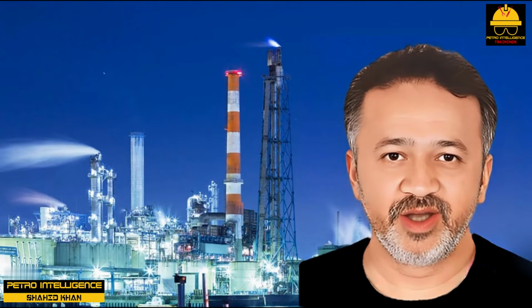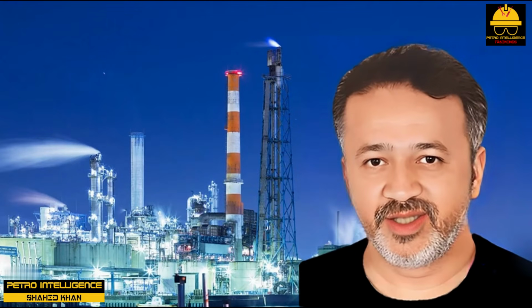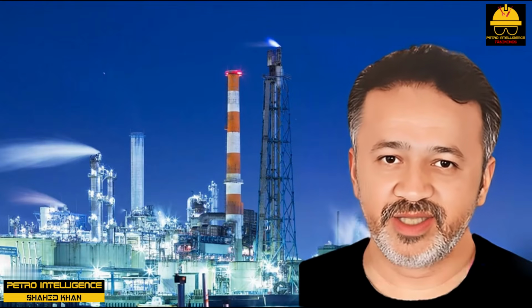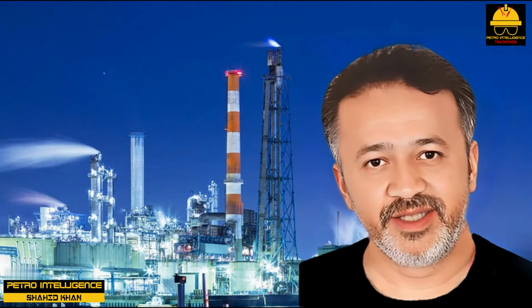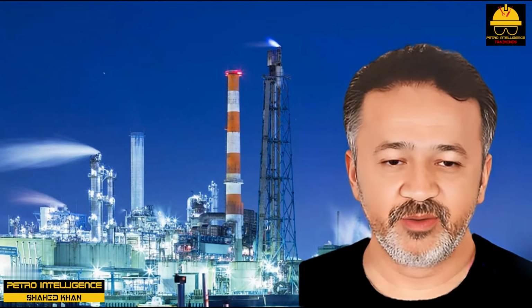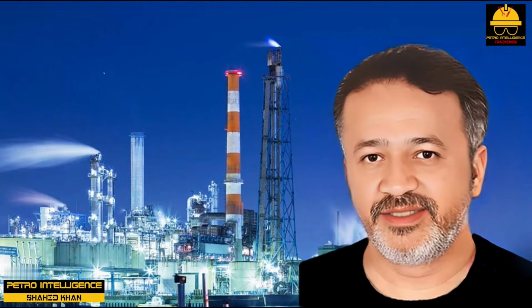Lubricating and seal oil often leak into the circulating refrigerant. The lower the suction pressure of the compressor, the greater the problem. Eventually, the amount of heavy oil that accumulates in the evaporator will cause a problem. The heavy oil is largely insoluble in the refrigerant. As the refrigerant boils away out of the evaporator, the heavy oil is left behind.